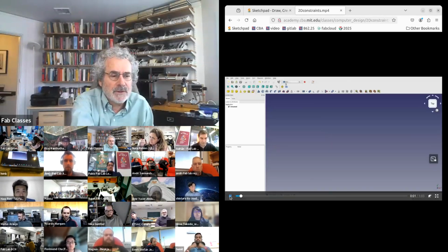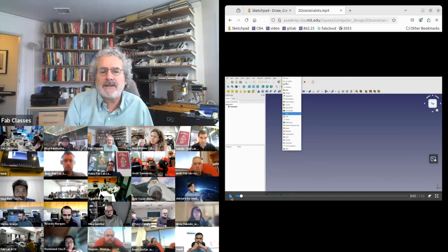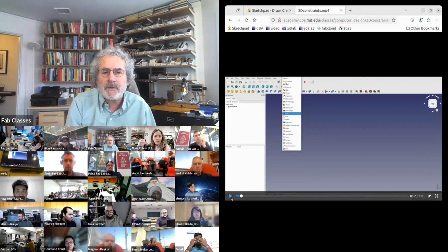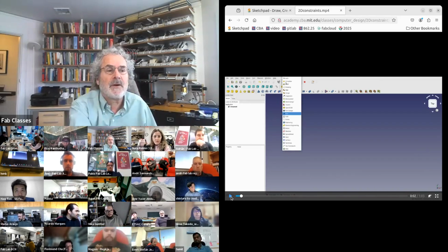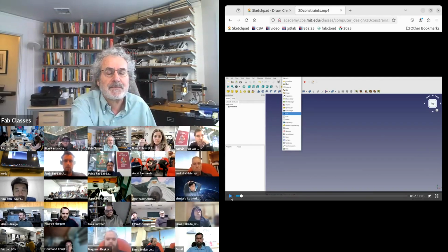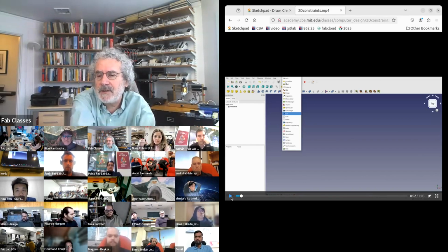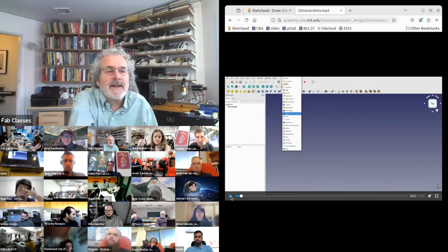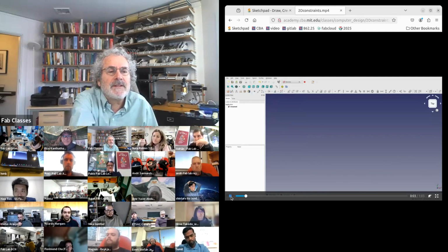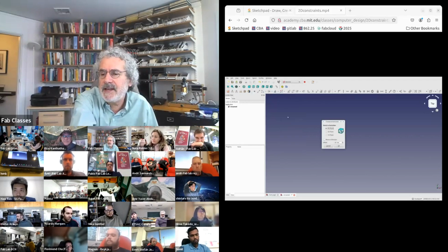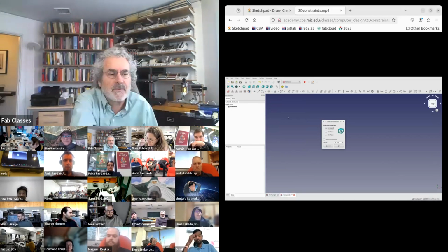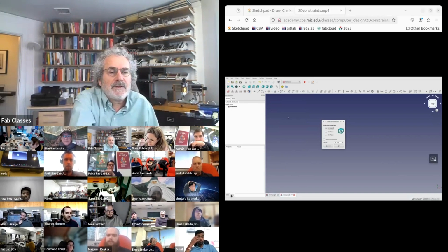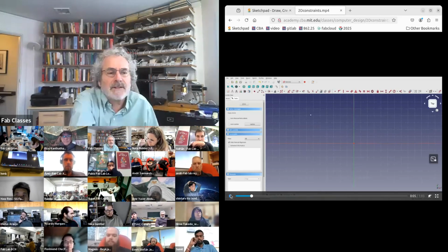This is going to introduce one of the most important concepts for today, which is constraints. So here I am in FreeCAD, and I'll talk more about FreeCAD in a minute for 3D. It has workbenches. So I'm going to pick a workbench for sketching, and sketching is the 2D drawing workbench. So I'm going to start a sketch.